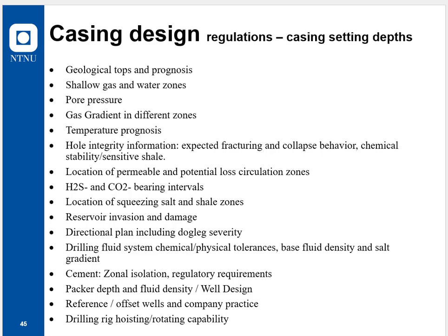Gas gradient in the different zones, temperature prognosis, integrity, and so on and so forth. H2S and CO2 would be very important because they both influence the material selection. Where there's squeezing salts or squeezing shales.